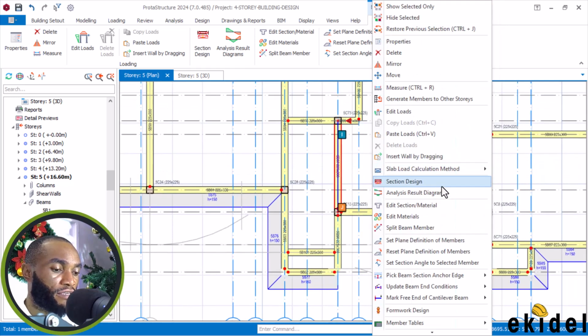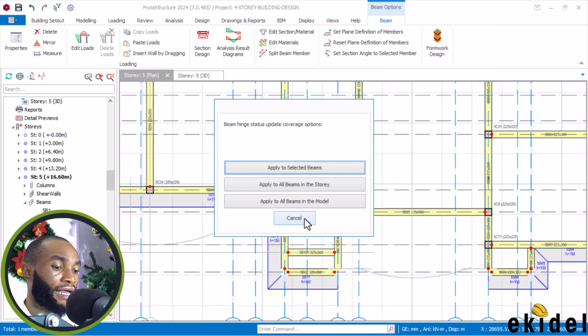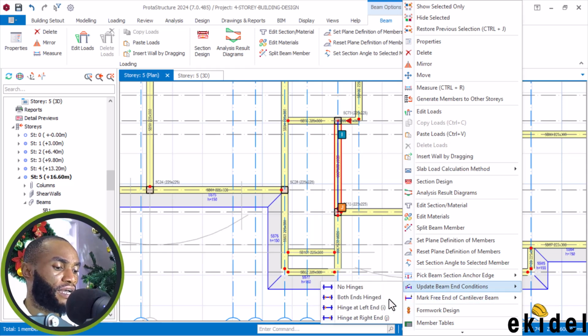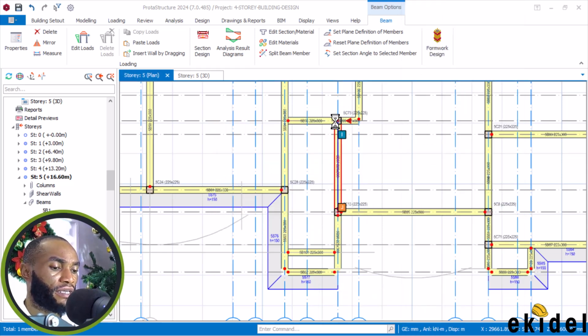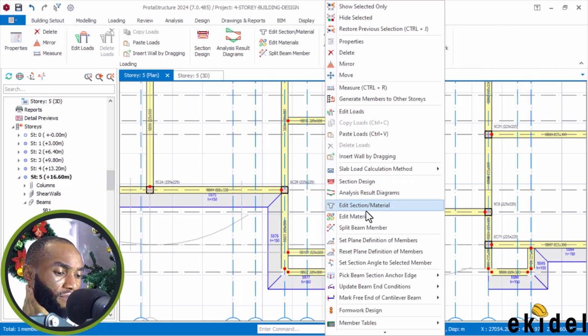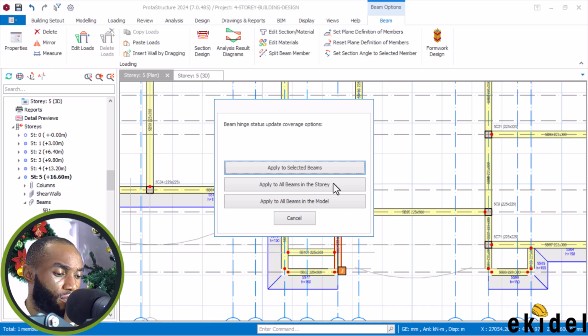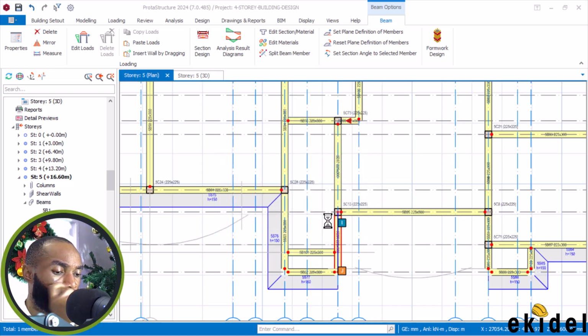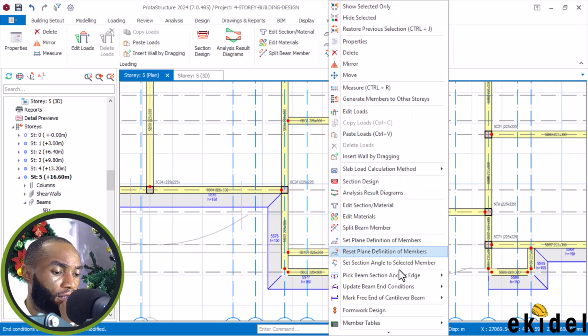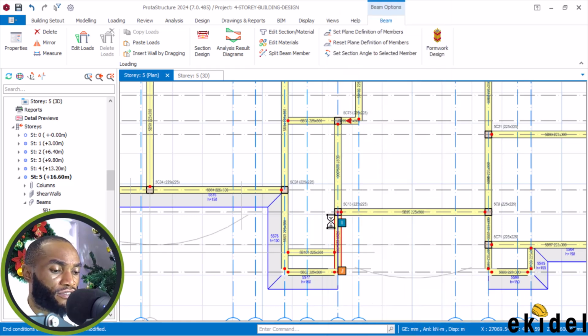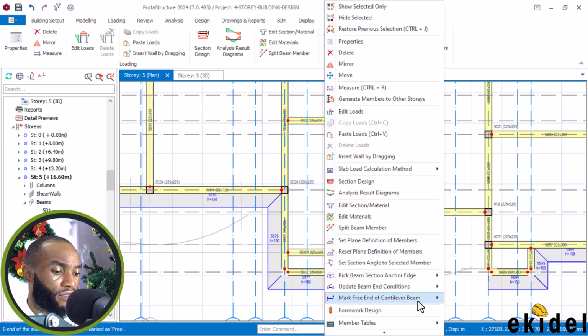Click on this, change the hinging to I end, sorry, cancel. Right click, I end here, transfer to this place. That's fine. Again, this place, no hinge, only cantilever. Right click here, no hinge, say yes, apply to slab beam. Then come here, apply to cantilever J end. That J end, I don't know, let me see that. No, just J end, sorry, that's J end. Come here, and then apply to J end.